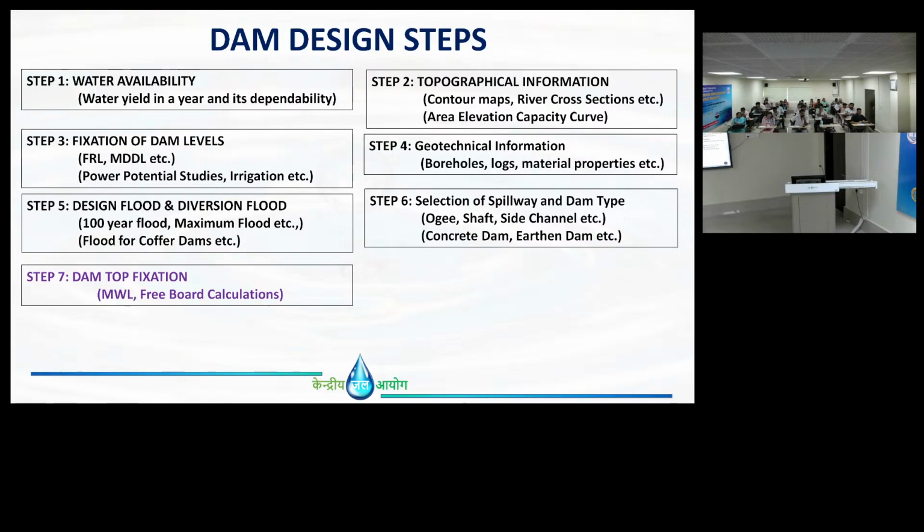See, like we selected these different spillways, right? Suppose, like I told, if you have enough river width, you can have the spillway capacity equal to inflow. But if you don't have, like, see, this is the river width, but here the width is very less. But in both cases the flood is the same.